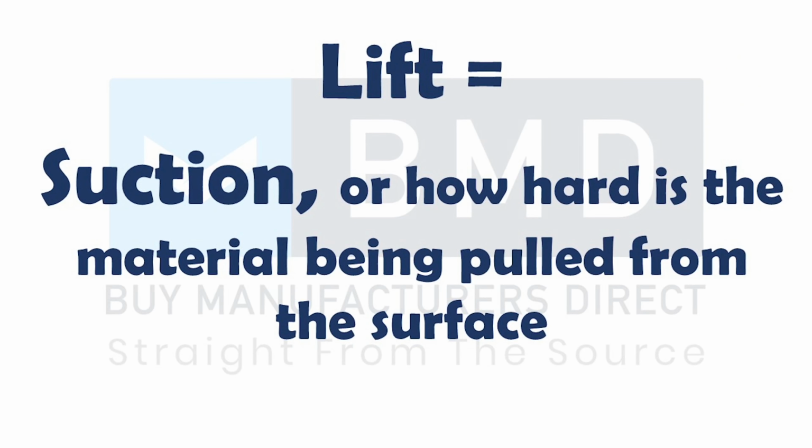Lift is just another measurement. Again, differentiating the differences between dust collection and a vacuum system. It equates to the suction or how hard you're pulling that material off of the ground itself. So again, you're using that lift to pull the material off the ground, and then the CFM is what's going to carry that through the hose.